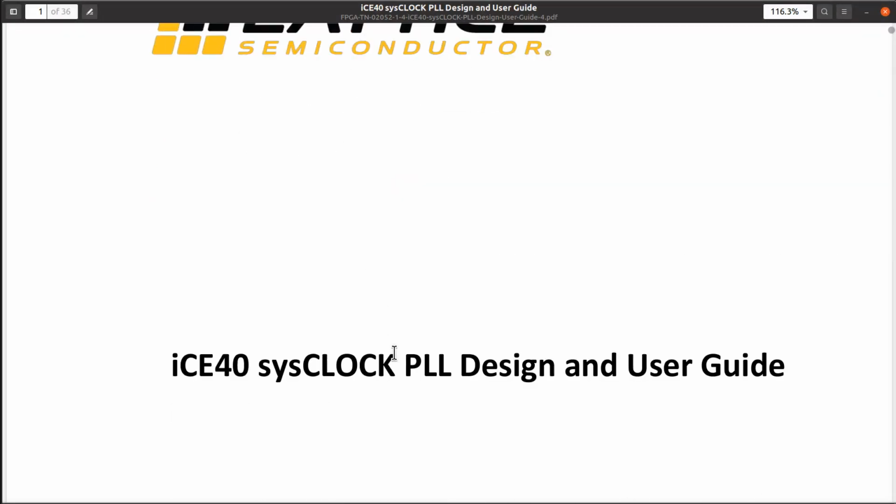So let's first of all understand what the heck is a PLL. PLL stands for phase locked loop, and it is an analog device that is inside. I don't know any FPGAs that don't have them. What they do is they take a clock, a free-running clock frequency, and they allow you to use a voltage-controlled oscillator and some counters and things like that to change the frequency.